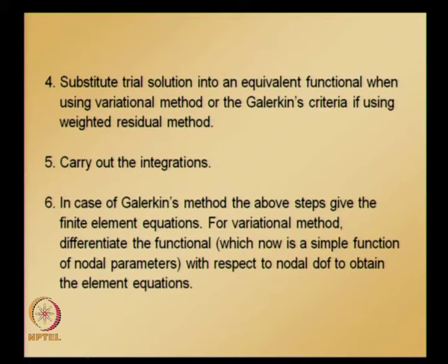So in today's lecture we will be looking at Lagrange interpolation formula for constructing finite element trial solutions, that is shape functions for second order boundary value problem, and also a basic concept of isoparametric mapping, where shape functions are used for transforming the physical element geometry into a parent element simple geometry.